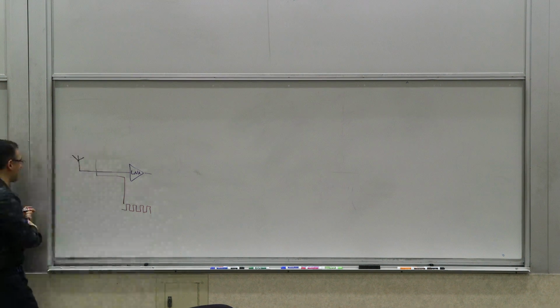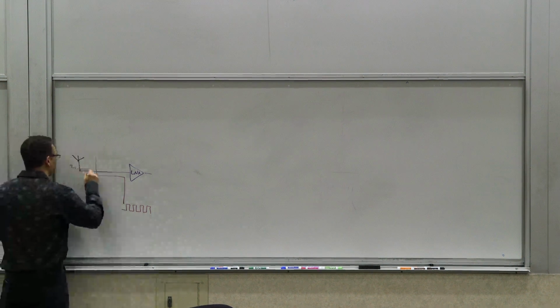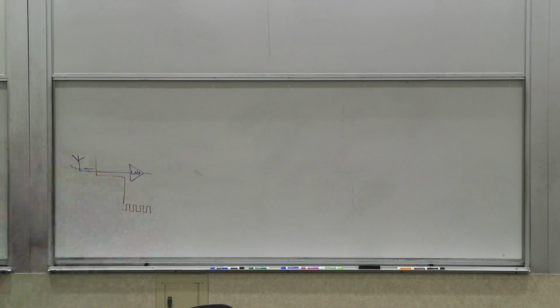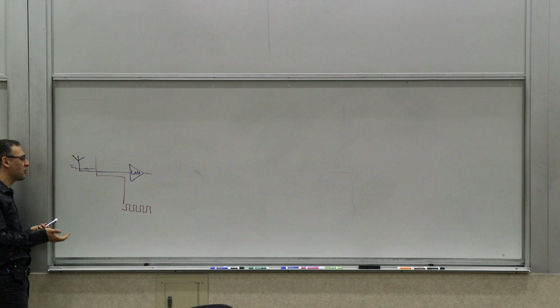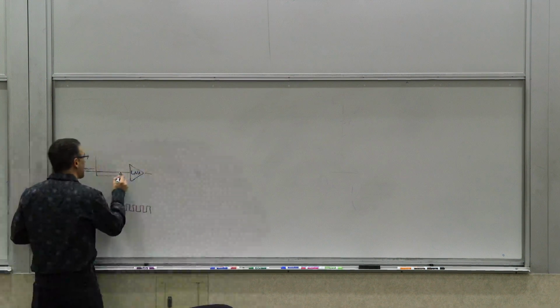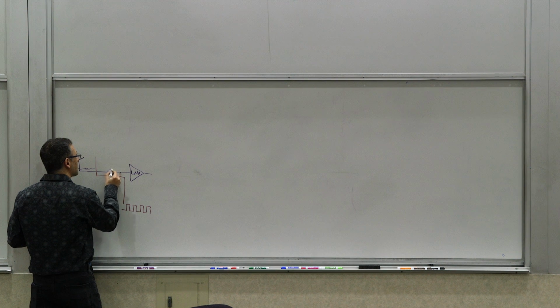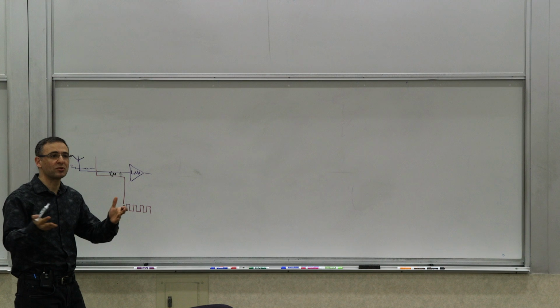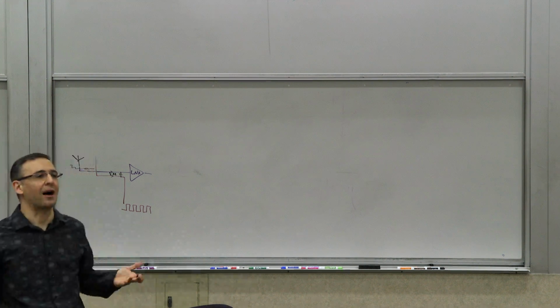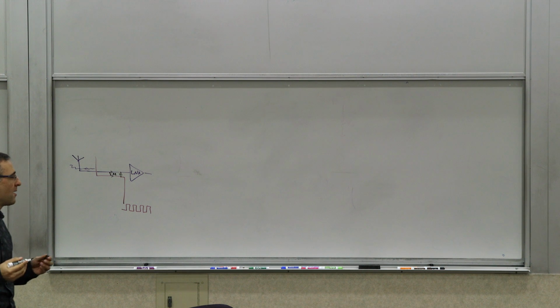So you have a weak signal arriving at your antenna, and you have this big digital clock next to it. And it somehow couples to it. Maybe it couples electrostatically, maybe it couples magnetically, or maybe it couples through the silicon substrate or something like that. So it couples somehow, right?